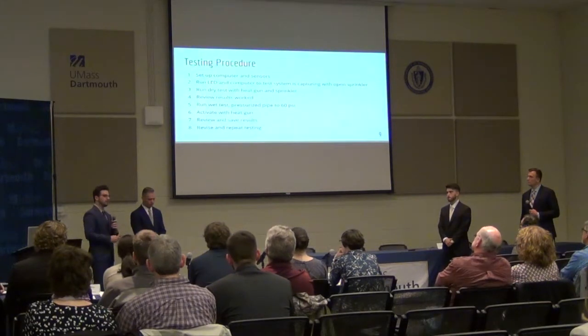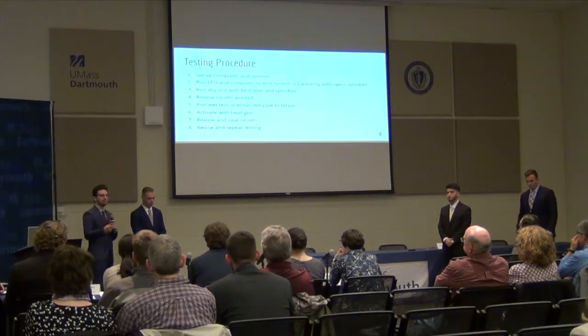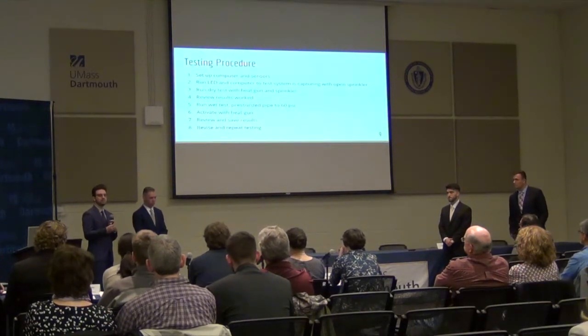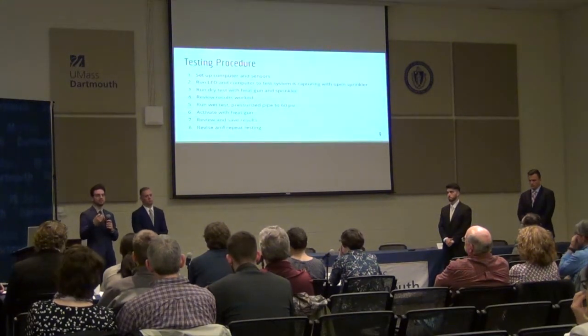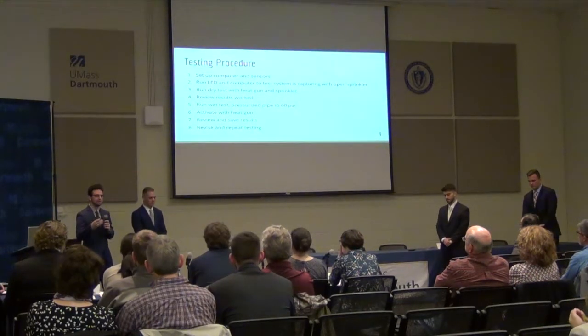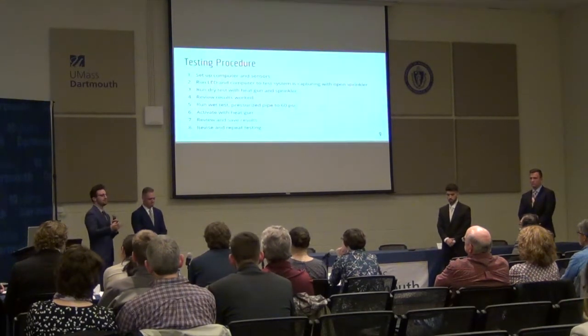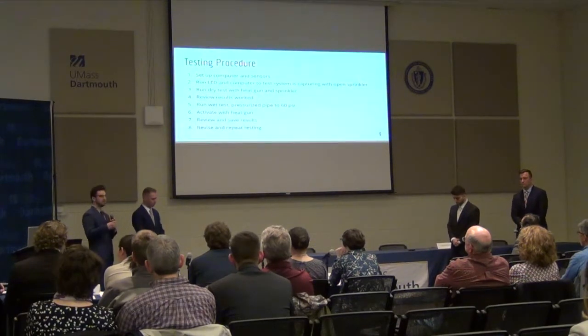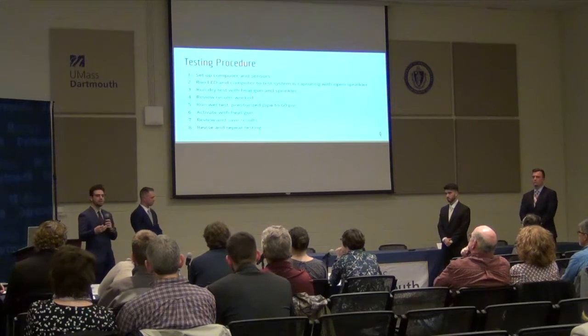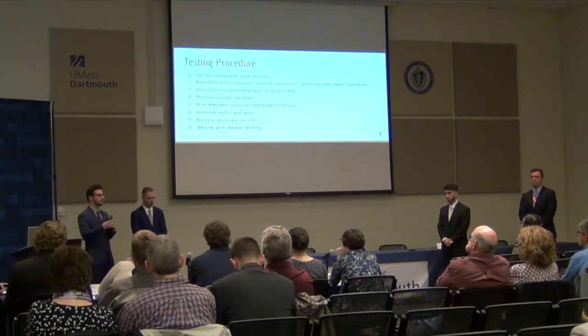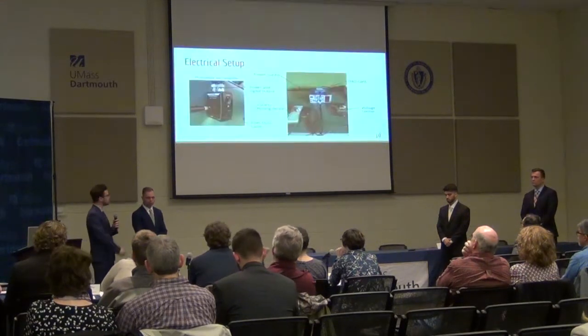From there we move on to a dry test, which consists of using a non-activated sprinkler but no water. We activate the sprinkler and then look for that jump in the LabVIEW, which I'll show later, just to get a timely validation to show that it was activated. From there we pressurize our pipe jig with water up to 60 psi, and then activate it, letting the water come out, and essentially evaluating the same values that we did for the dry test.